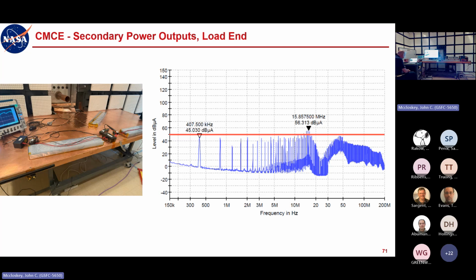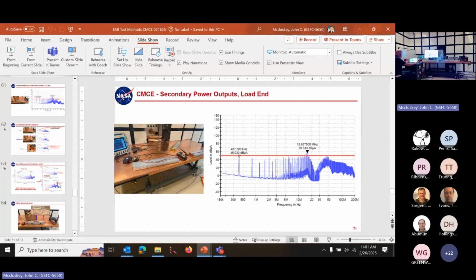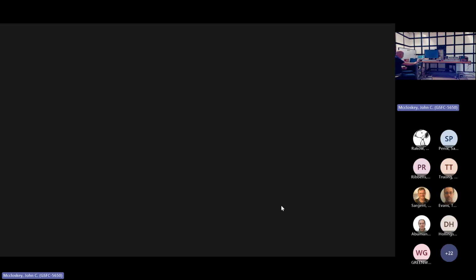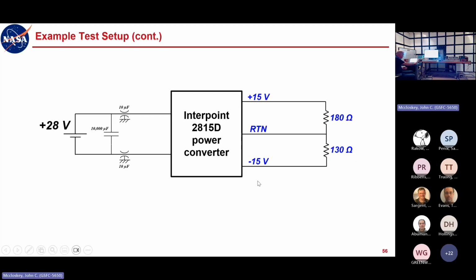So it's affecting the low frequencies too. And just thinking about that since Monday, there's a discussion we had on Monday. I don't know if Ed Chung is on the line again, but Ed brought something up that I didn't fully click until after we were done. But you have distributed capacitance here, right? If it's truly an open circuit, you shouldn't see any current at all, any common mode current. That's clearly not true. We do observe it. It's whatever capacitance you have between this and your ground plane, but it's distributed capacitance all the way across here.